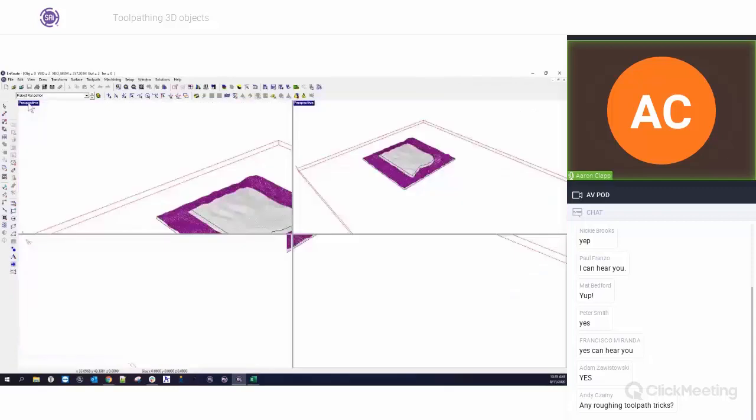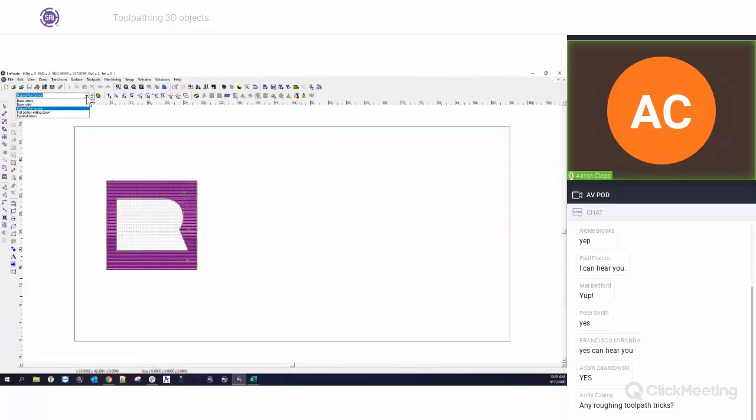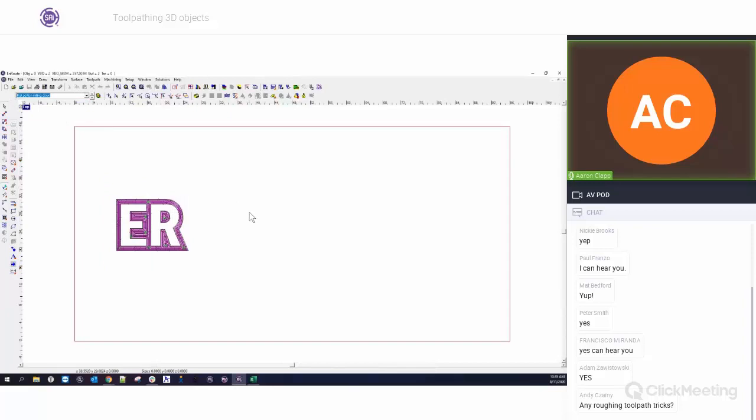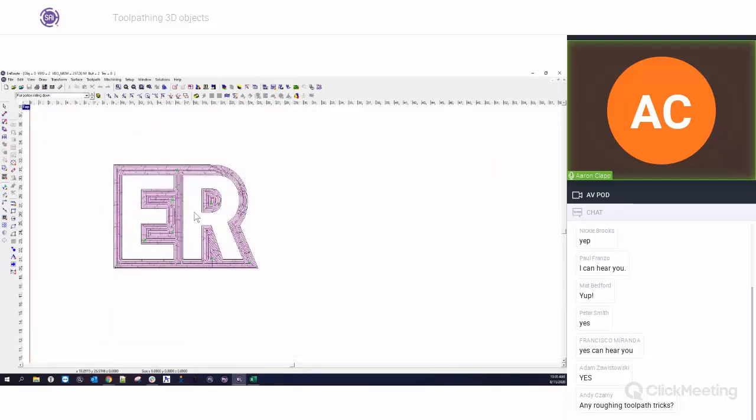So we'll go back to our main view here. I'm going to go to my flat portion milling down. So you can see here what I've done is I don't actually have a relief at this point. I'm not even applying this to a relief. I am just simply taking an island fill. I'm using a mask or inside, outside, or whole container system here. And I'm creating a contour cut around these letters so that this base gets milled down just a little bit.